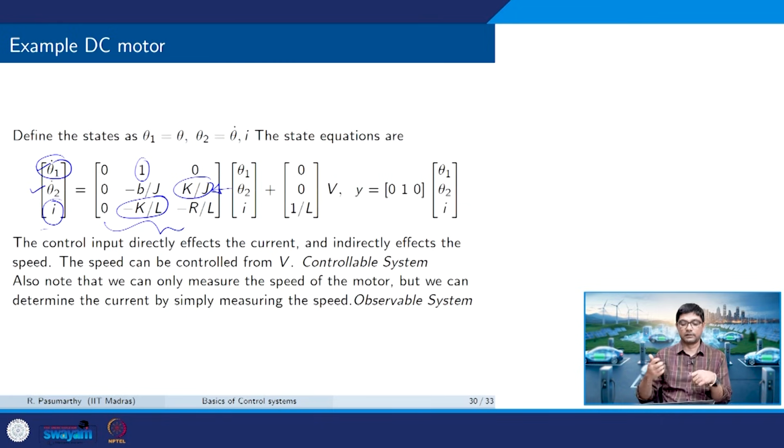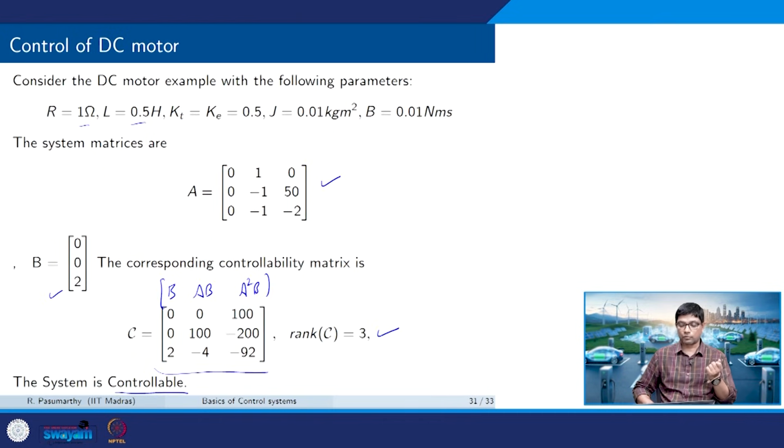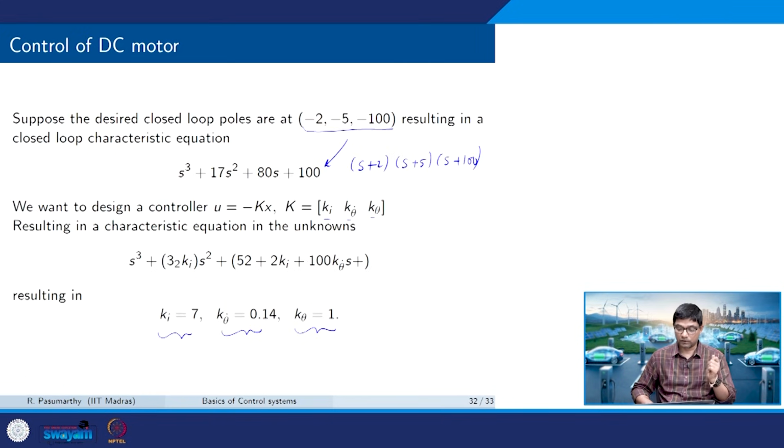I am just interested in controlling the velocity through the current, and I can just do a state space model which is just two dimensions, right? I don't really worry about what position my motor is at. Of course, for certain servo applications which we might see, we may need some of this extra control, but again the controller depends on what problem you are trying to solve.